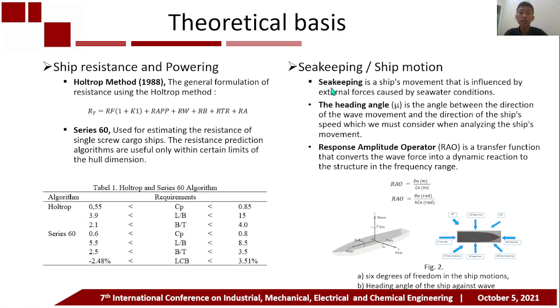Then we go to the seakeeping of ship motion subchapter. Seakeeping is a movement that is influenced by external forces caused by seawater conditions. There are two main parts of seakeeping. The first is heading angle and the second is RAO, also known as response amplitude operator. Heading angle is the angle between the direction of the wave movement and the direction of the ship's speed, which must be considered when analyzing the ship's movement.